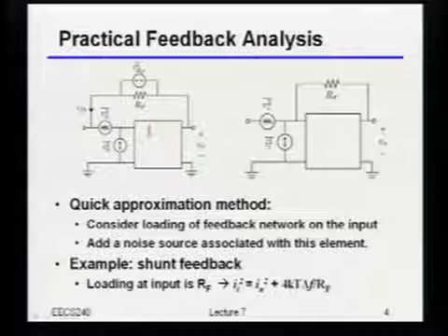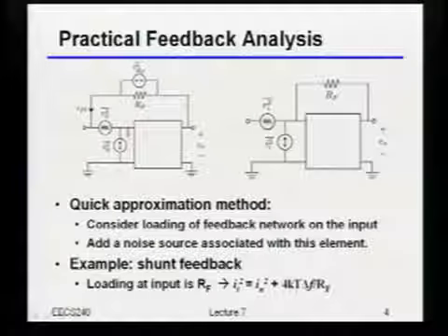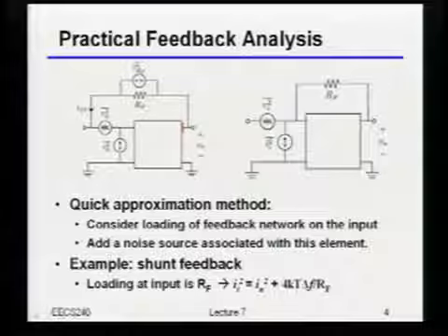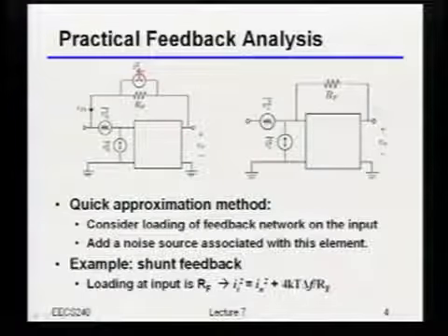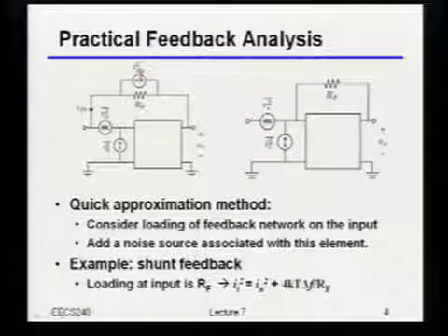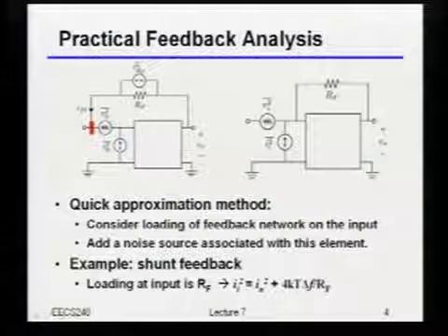Well, if that's the case, and assuming that I've got a good feedback loop, meaning I added this shunt resistance because I had a pretty high input impedance to begin with, and I have a good amplifier with a low output impedance, then the quickest way to approximate this is to say that all of that noise current is just adding directly into the input, right?